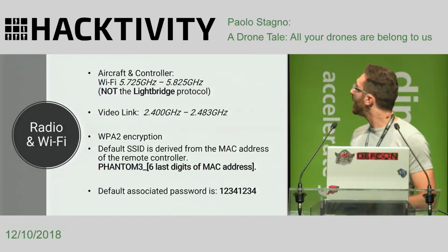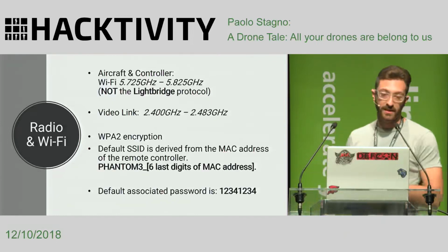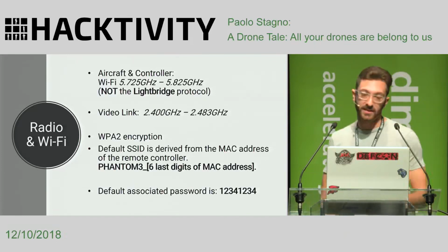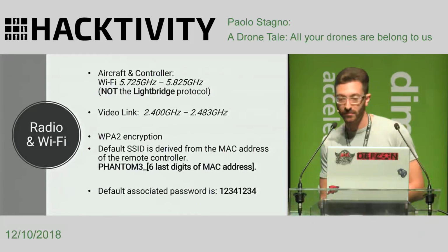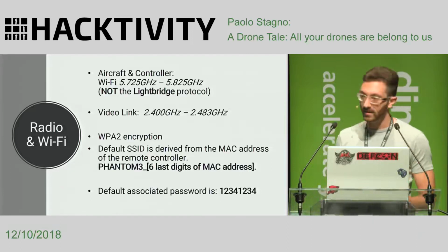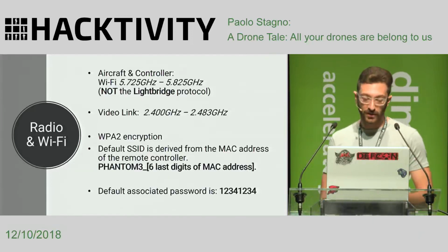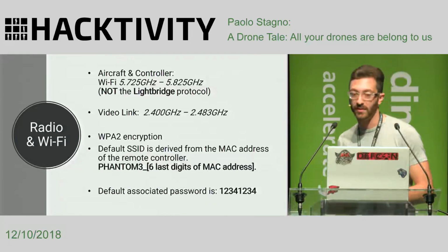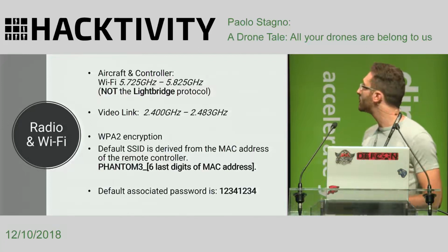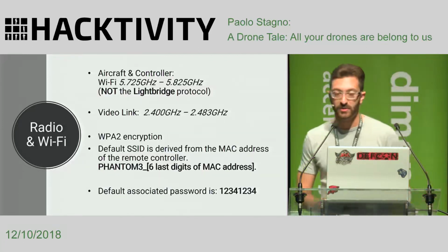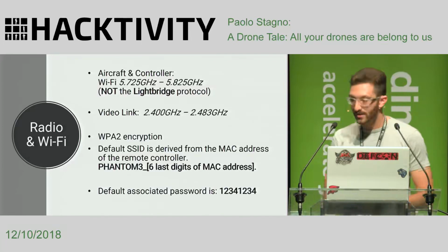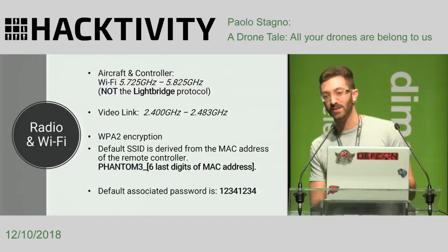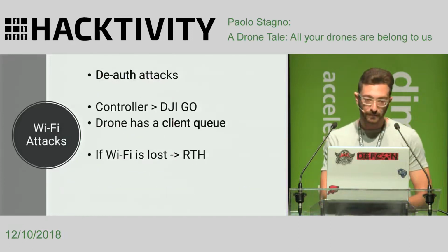While on this one, the Wi-Fi standard is WPA2, and the default SSID is derived from the MAC address of the remote controller, following this format. It's Phantom3 underscore, the last 6 digits of the MAC address. And the default password is the evergreen strong password, 1234, 1234. So if you don't change it, anyone can connect to your network and exploit some other functionality of the drone.